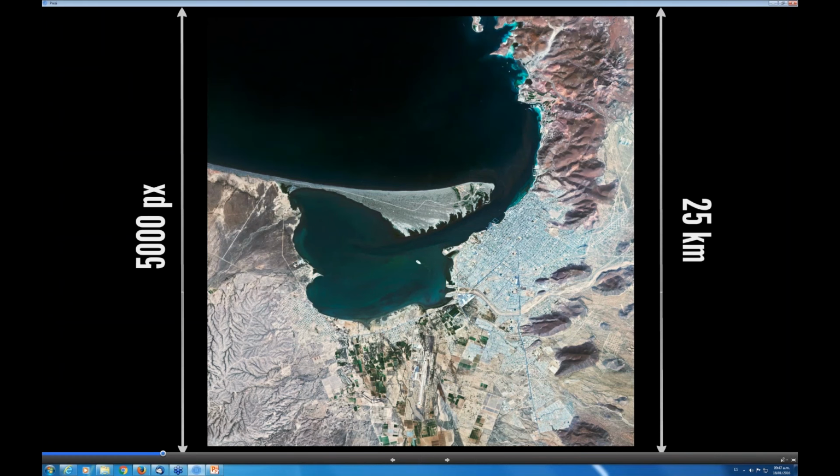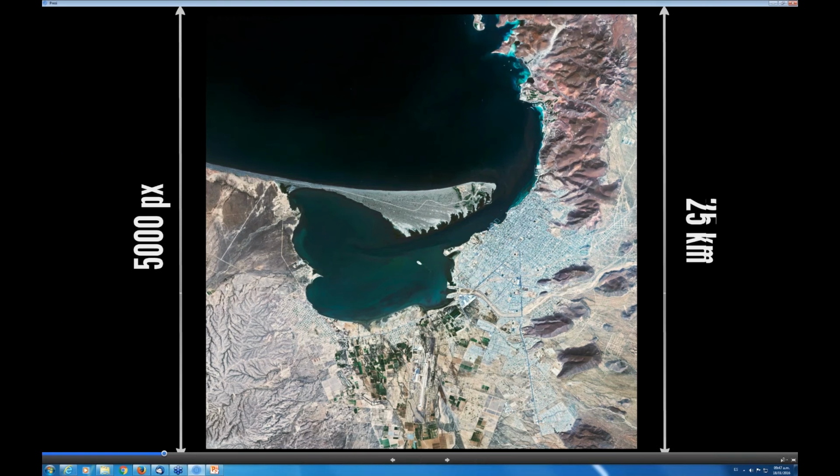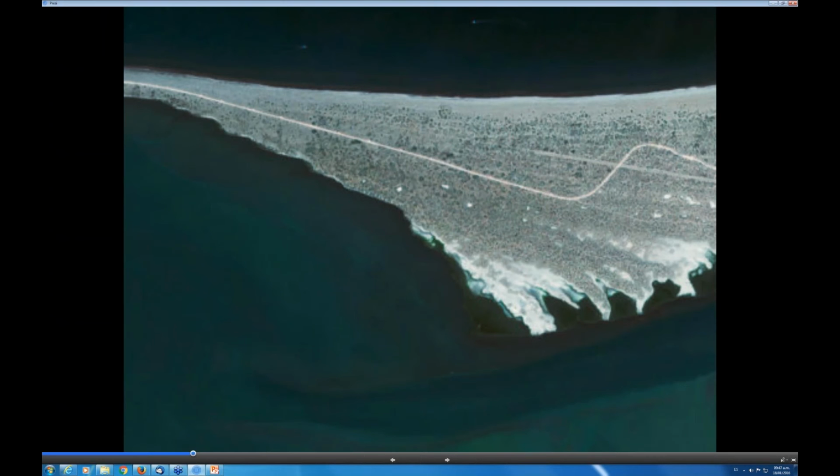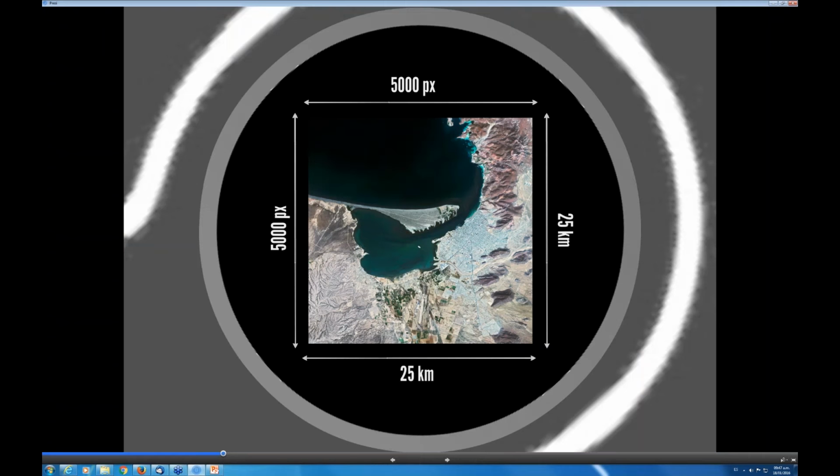Andres already mentioned this. So we don't use the highest resolution data available today in the market, but let's zoom to the full resolution. Anyway, we are at a very high level of detail, so we can distinguish, for example, different vegetation elements, including single trees. Having a resolution of 5 meters per pixel, a RapidEye scene has 5,000 times 5,000 pixels. So each scene covers an area of 25 square kilometers. Now, Mexico being number 13 in the list of the world's largest countries, we have almost 2 million square kilometers to cover. So we need approximately 4,500 scenes.